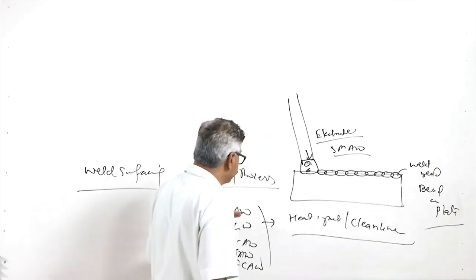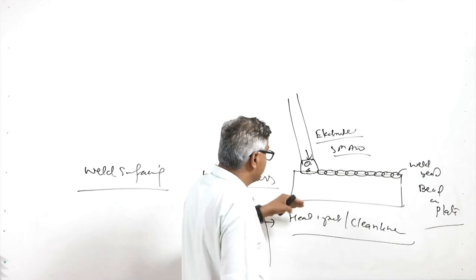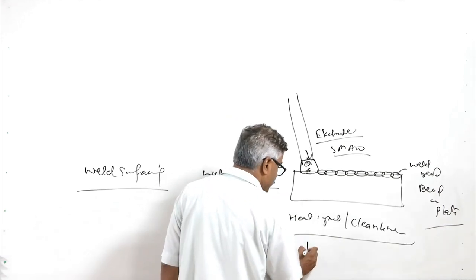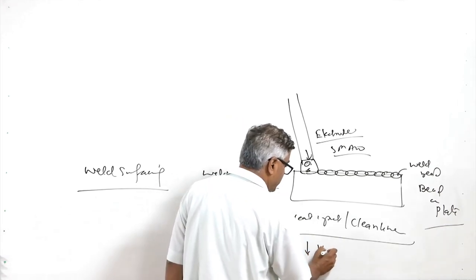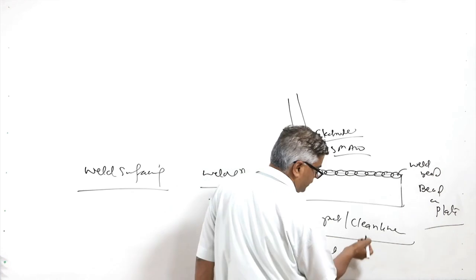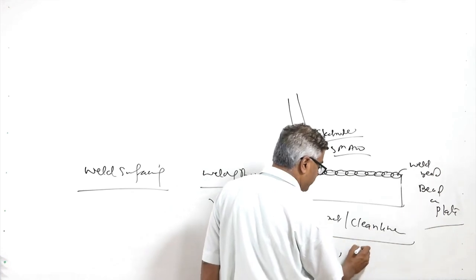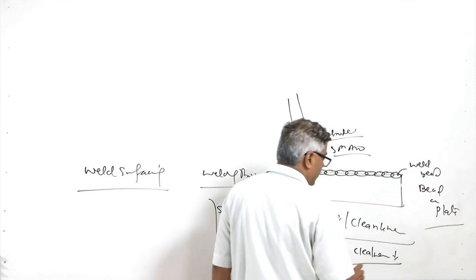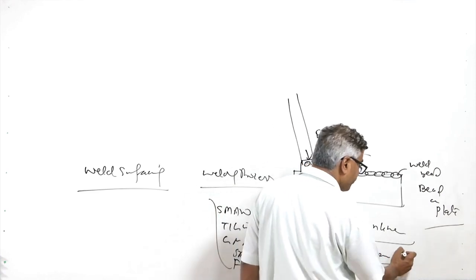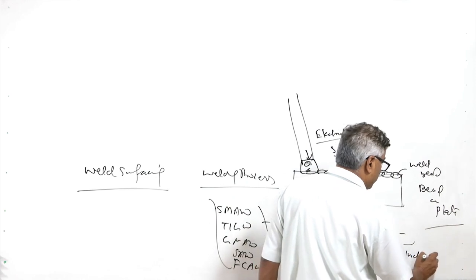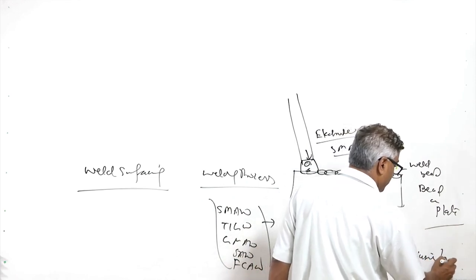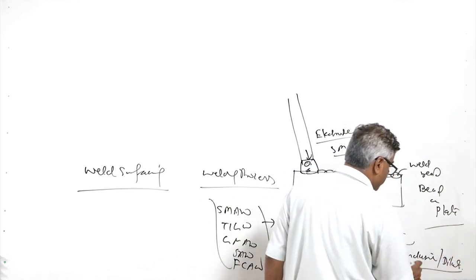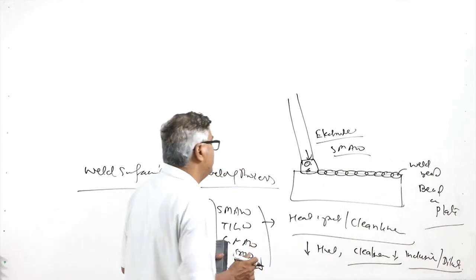The weld surfacing deposited using SMAW has less control over the heat input, and the cleanliness of the weld is also less. Because of this, we will have a greater amount of inclusions and higher dilution levels, because control over the heat input is limited.